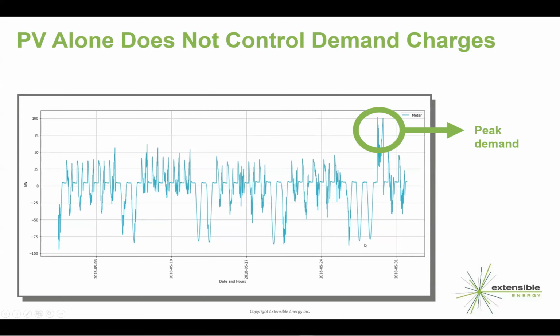This building was using no energy to speak of over a long weekend. So the energy management system, which was working perfectly, mind you, was saying, I'm conserving energy, I'm saving my owner some money. And yet it was a hot 3-day weekend, and the building got very warm inside.